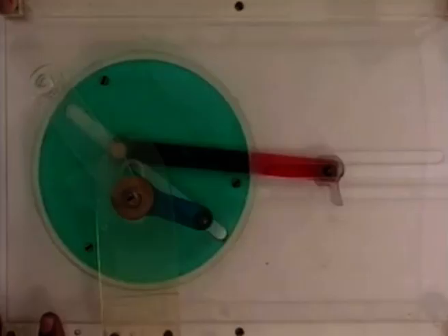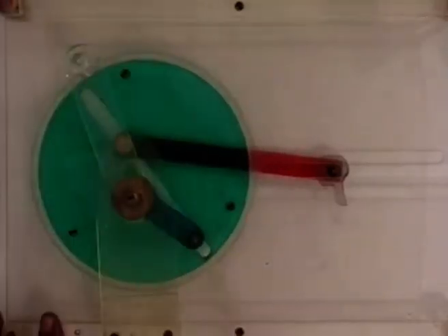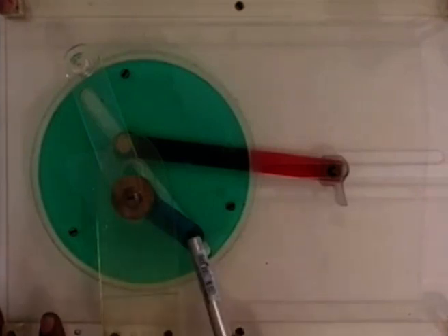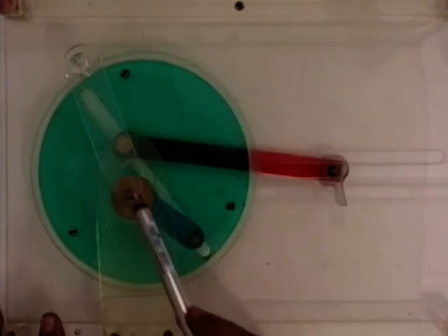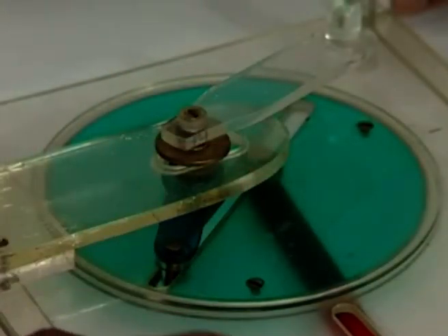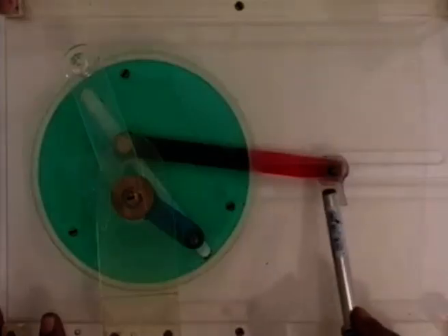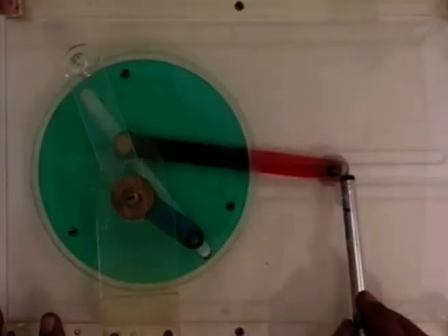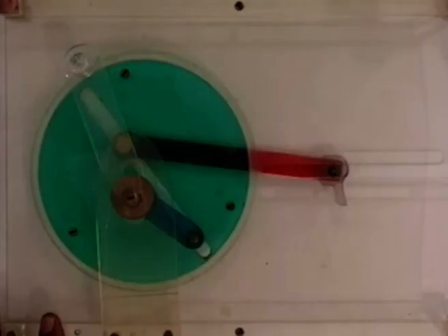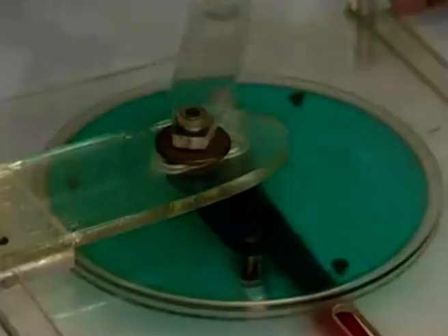Our job is, given this 6-link mechanism at a particular configuration, first to locate all the relative instantaneous centers. Second, given the input angular velocity omega 2 at this configuration, what is the velocity of the cutting tool or this tool holder, that is this slider, which will be our link number 6? This is the problem that we are now going to solve.